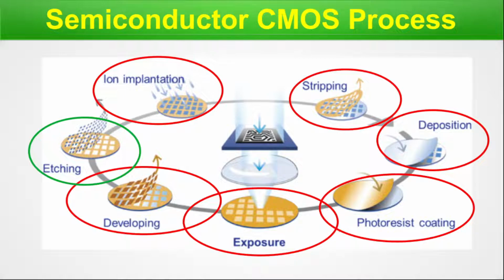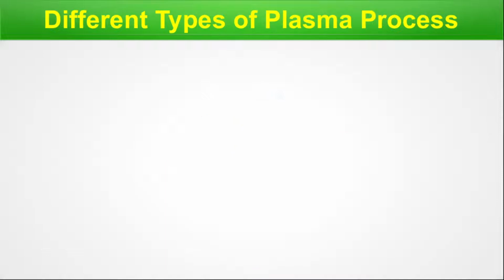It keeps on operating for formation of the metal routes in the BEOL region I have shown in the first slide. The FEOL and MEOL obviously go through this process. However, the BEOL goes through this cyclic process several times, and the step marked in green, etching, is the process step where we are using the plasma, and here are the chances of getting the antenna effect. Don't think that antenna violation is happening to only metal one. It can happen in any of the metal layers as shown in the picture where I have marked the BEOL layers. We're done with this particular slide, so let's move on to the next slide.